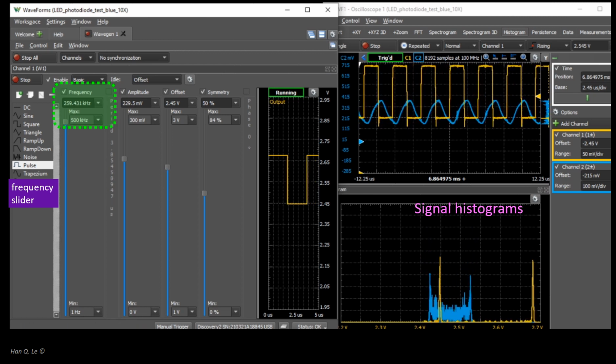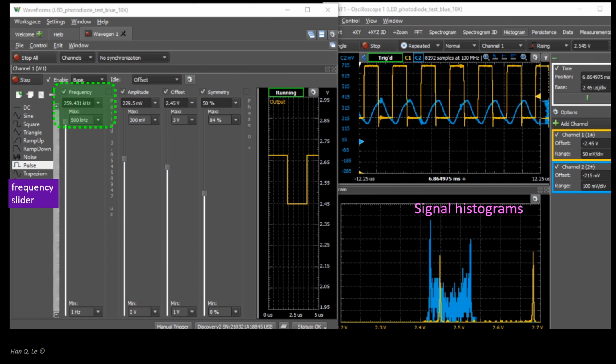A relevant question is what limits this bandwidth: the LED, the photodiode, or the op-amps. As the voltage amplifier frequency and impulse responses were tested in Part A, the results indicate that the 741 op-amp, which is designed for audio applications and among the slowest op-amps, alone accounts for this bandwidth. Based on the specifications and known properties of this type of LED and photodiode, their bandwidths are much higher, up to a few tens of megahertz. Hence, this optical receiver test is more of a test of the 741 op-amp rather than the optical devices.